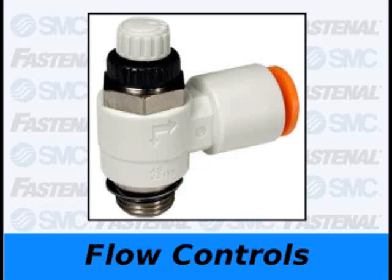In the same way it's not good to drive your car at full speed, it's usually unsafe for the operator and damaging to the product quality to run the actuators at full speed. That's where flow controls fit in. They go in the tube between the control valve and the air cylinder or actuator, and the knob on top lets you set the optimal speed.